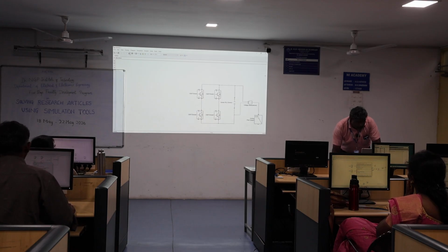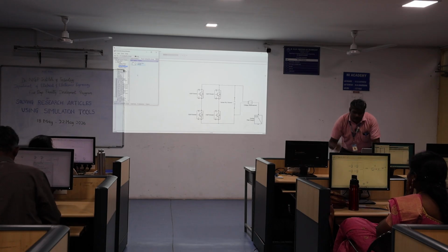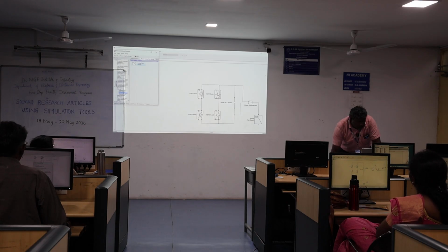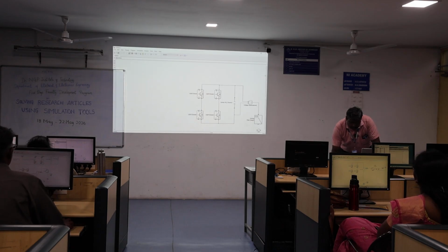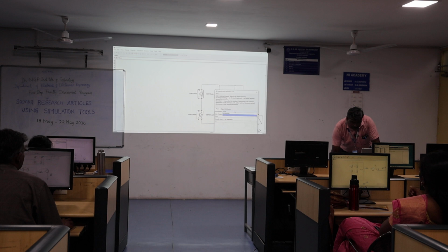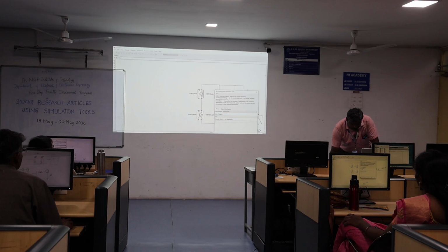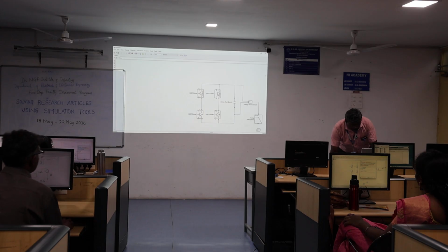Next you need to take the difference between the measured value and the reference value. Then we can go to the commonly used Simulink blocks and take the sum block. Here the sum block is available, right? Take the sum block. Then you can change the sign, instead of plus change to minus. Then control R, rotate.